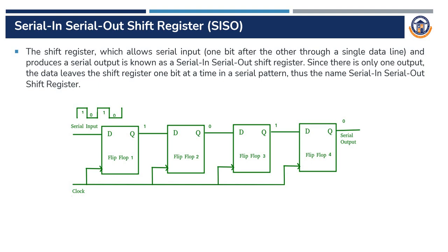As the name indicates, a serial in serial out shift register will shift the data serially, and the data is taken from all the flip-flops connected together in the shift register serially. The flip-flops are connected through a common clock pulse, so it is a synchronous shift register.